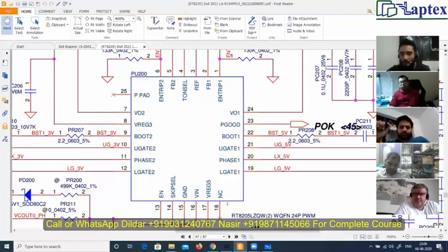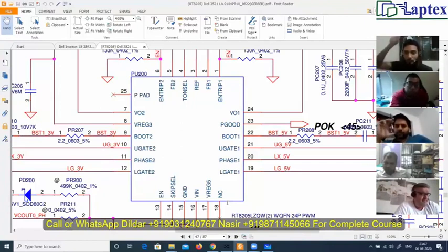So that's why I'm telling you, don't just see the number RT8205 and put the IC here and then ask me why it is not working. You have to understand which pin is working for what purpose and match that as well. If it is no connect and you have used RT8205A, you have to lift that pin up from that point so that it is not used there. Then you can use it if all the pins are matching.